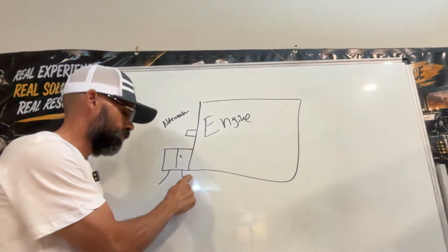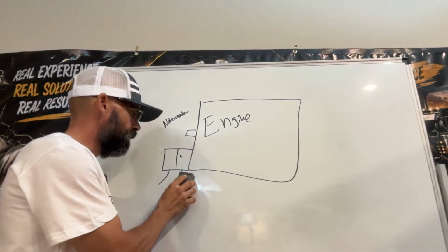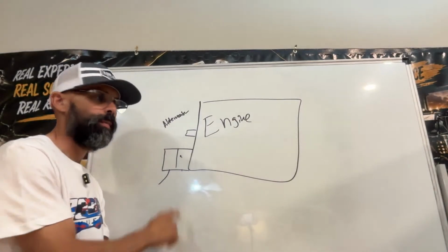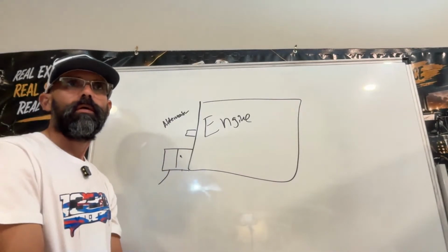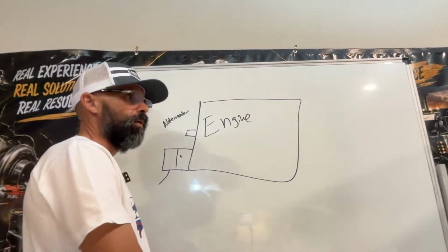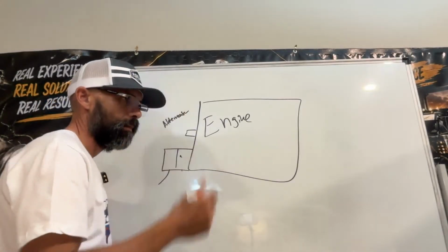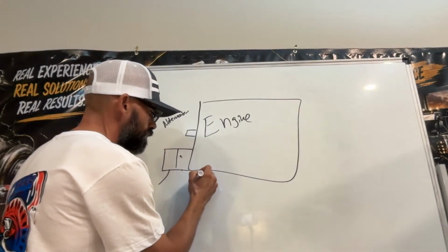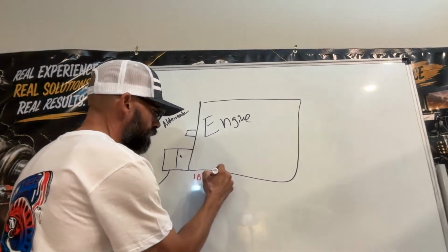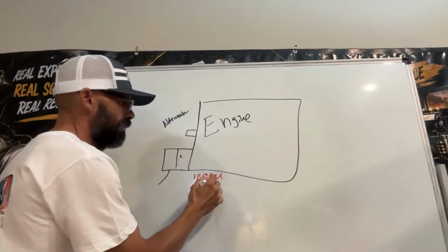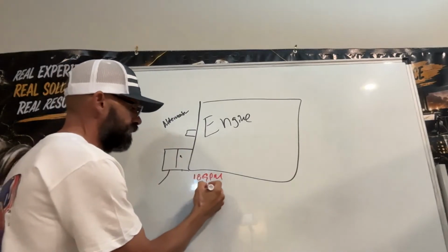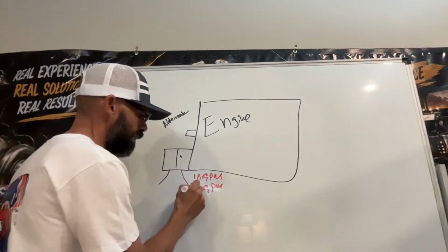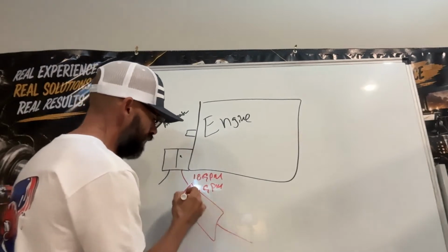Because if the manufacturer, if Casappa, most of these pumps, or Eaton, they call out for, let me say an example, 18 GPM, right? 18 gallons per minute, and you're only getting 6 GPM when you put a flow meter,